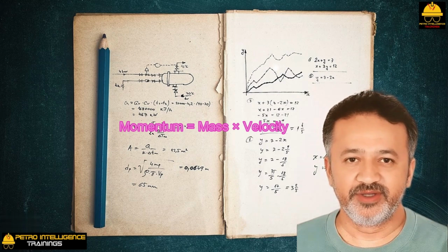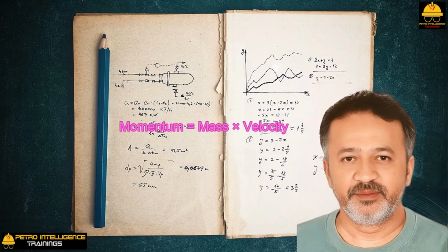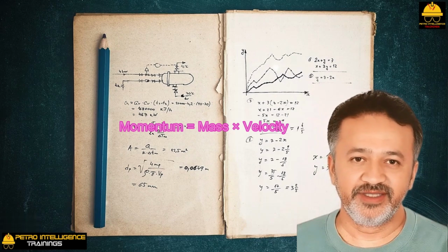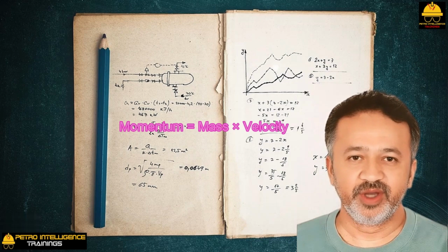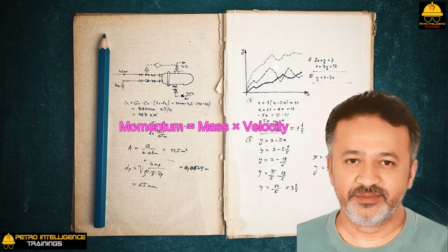You can see quite clearly that it is not the pressure of the steam that is driving a turbine. Place a pressure gauge on the turbine case of a single-wheel machine. The pressure on the turbine case will be quite close to the exhaust steam pressure and certainly not the motive steam pressure.